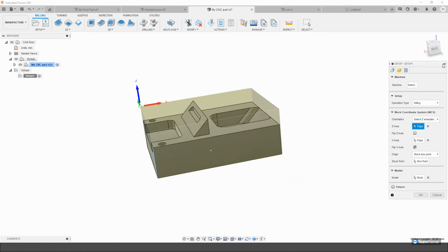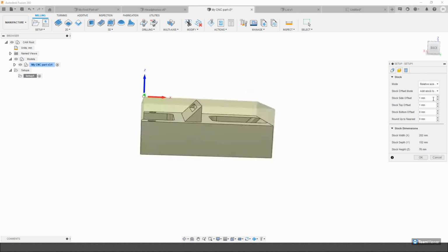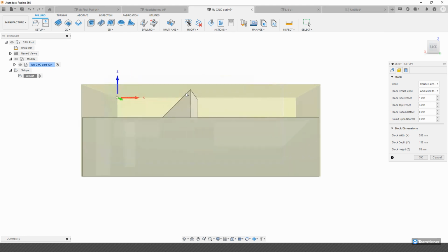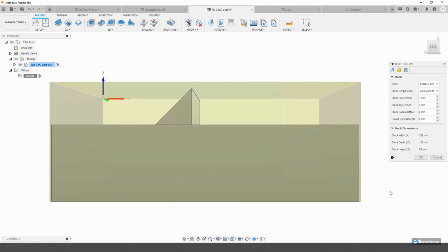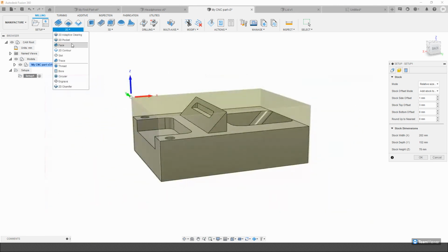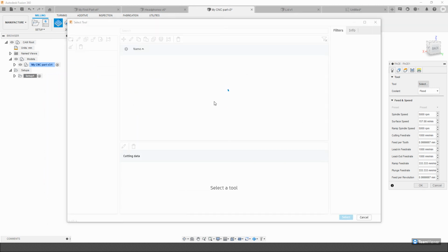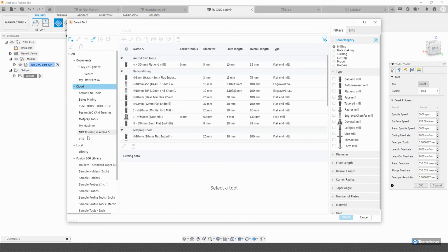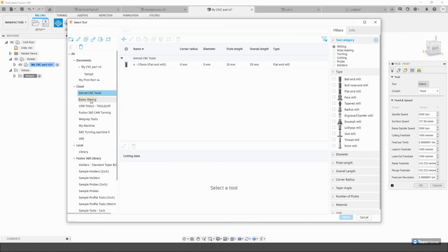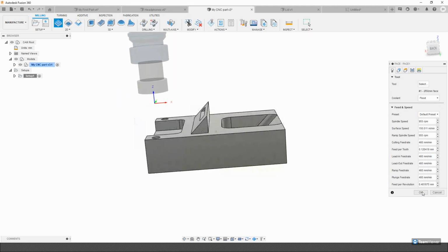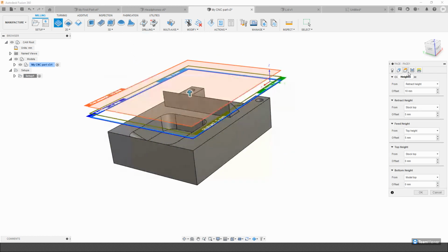So for example, if in my setup I had maybe a couple of mills on the top. So if you look at the top, I'm adding a few mills to the top. I'm just going to change the display like so. So if I look at the top, I've added 3 mills. If I want to do a simple facing operation, I'll say, all right, let me do a face. I'll choose a tool. Where can I find a tool? Right, and I'm going to say face off this within this bounding box.